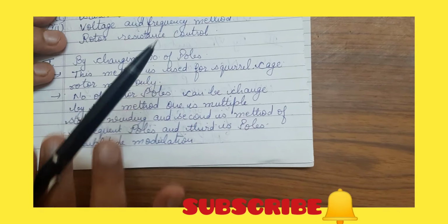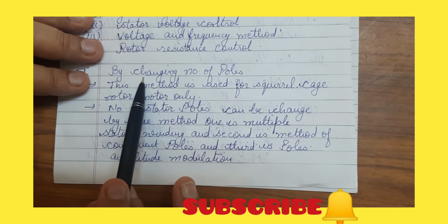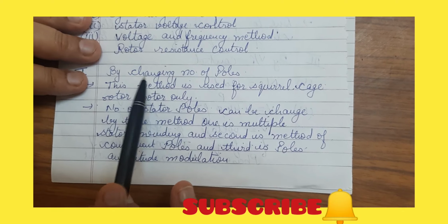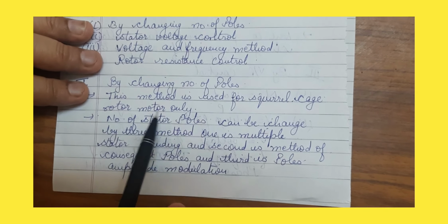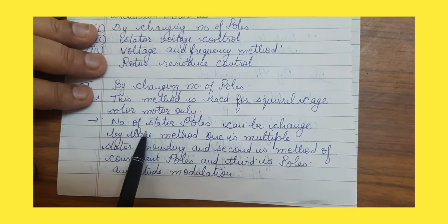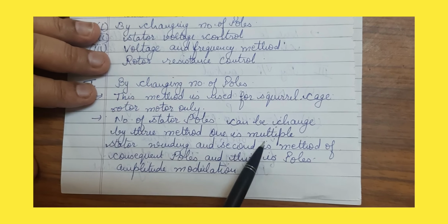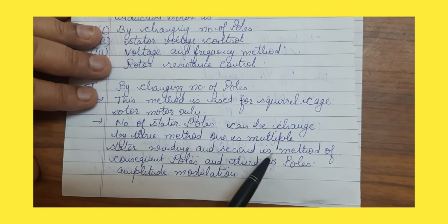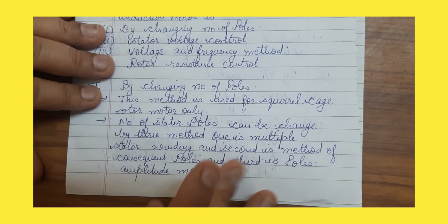So how can we control the speed of the induction motor? By changing the number of poles. It is used for the squirrel cage rotor motor only. The number of stator poles can be changed by three methods: one is multiple stator winding, second is the method of consequent pole, and third is pole amplitude modulation.